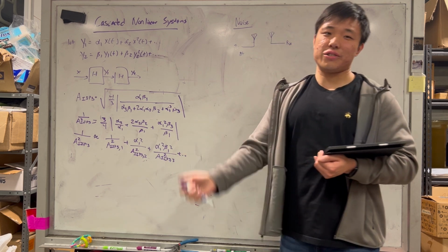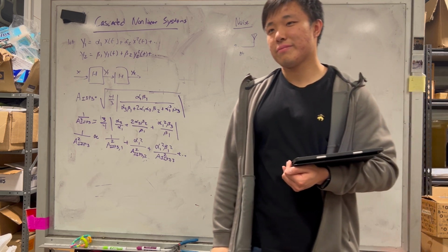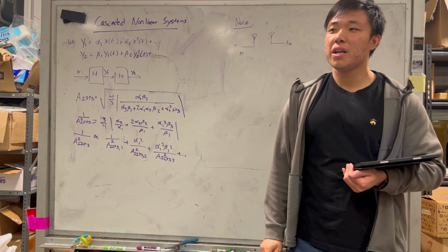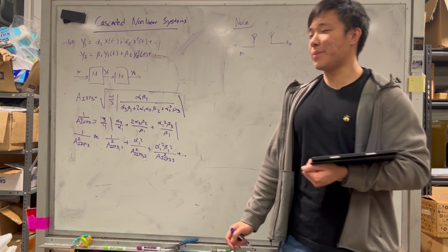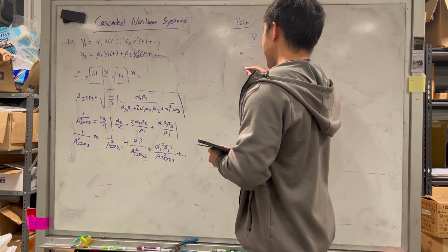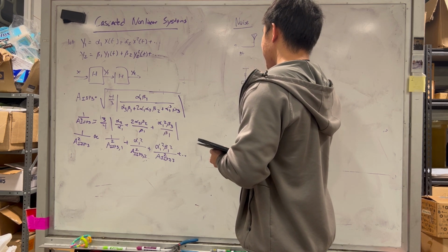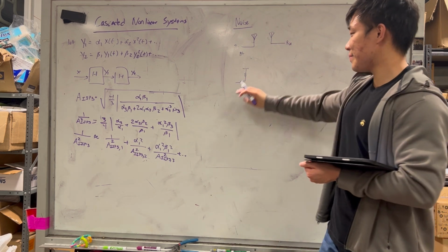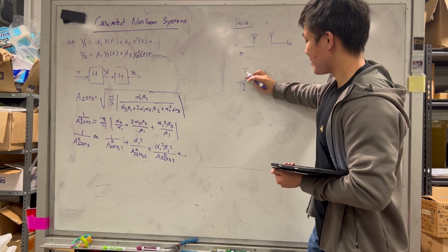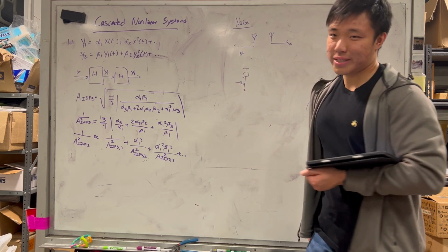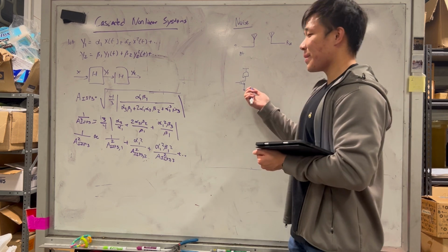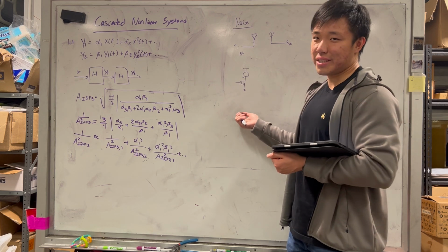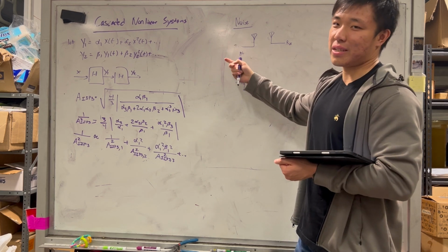just like a general question, if I had some system, some MOSFET, let's say some MOS amplifier of some sort. If I want to make it more linear, let's make the most basic device, something like this. If I want to make this more linear, what do I have to do? You know what? I'm just going to call this a black box. All right. If I want to make this more linear, I pump more current through it. Right, I make gm better, right? So that's why you want to pump more power into it to make the system more linear.